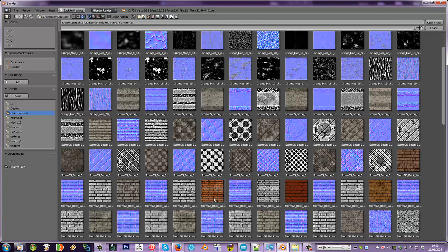The coloured looking image of a brick is referred to as a diffuse map. The purpley blue weird looking thing is called a normal map, and that's used to add fine texture to a surface. And the third one is a specular map, which is an image which describes which bits are shiny and which bits aren't. But we'll start off by putting the texture map on.